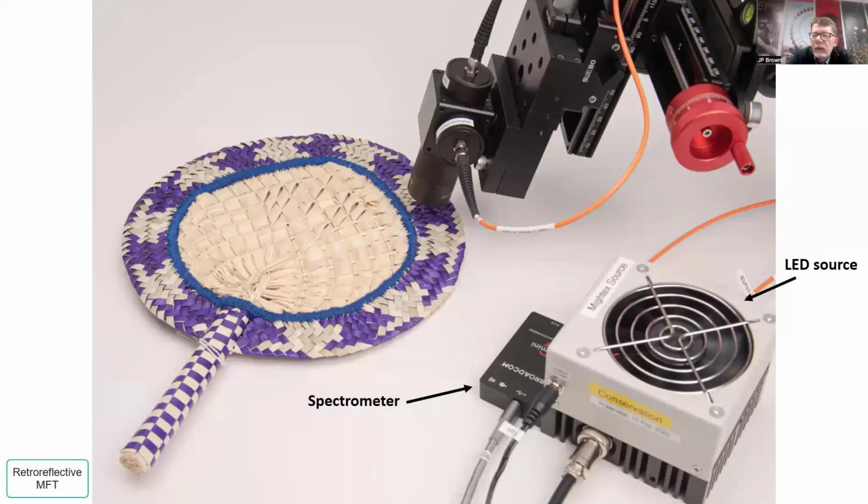The spectrometer is lying flat on the table at the left of the Mitex LED source. Now, as I said, the source is actively cooled, which is great for stability, but the cooling fan sucks air in through the top of the controller, and the warmed air is blown out through holes on the sides. So if equipment is arranged like this, the effect is to increase the temperature of the spectrometer.